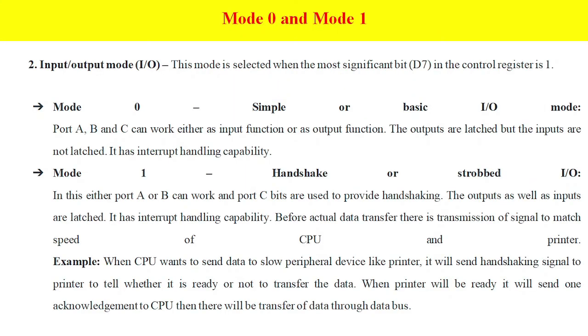Next is input output mode, mode 0, mode 1. So mode 0 is simple or basic IO mode. In this, port A, B, C can work either as input function or output function. So the outputs are latched, but the inputs are not latched. It has interrupt handling capability.